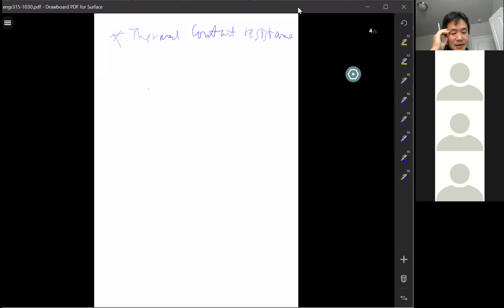Good. See, you have two materials, A and B. The lengths are delta XA and delta XB for the two materials, right? When they are in contact, the heat is transferred from left to right. So now you know temperature linearly decreases in the material. In conduction, the heat transfer rate is kA dT/dx, right? It's a first order derivative, so it changes linearly. It's a decreasing straight line.